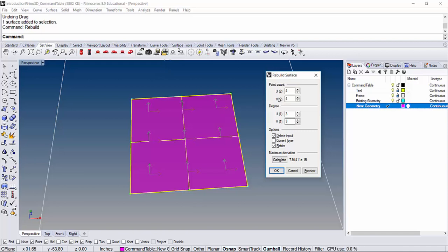Does that make sense? So there are relative coordinates for a surface, which we define as u and v, and w if we have thickness. And there are world coordinates, which are x, y and z, which are always calculated relative to the origin. Working with u and v allows us to look at a surface as a two-dimensional domain. So what is a domain? A domain is something that has a start and an end, right? If this is my surface, this could be the start. I could say this is my u direction, this is my v direction, this is 0, and that is u and v, right? So that becomes a way for us to define a surface.